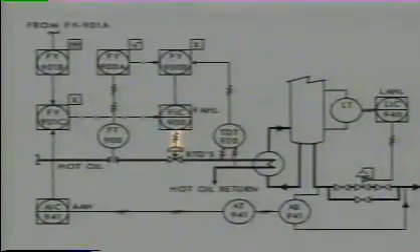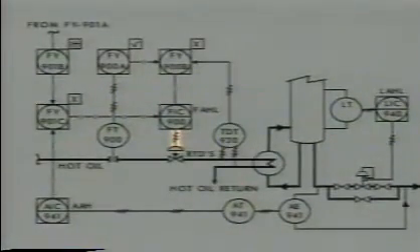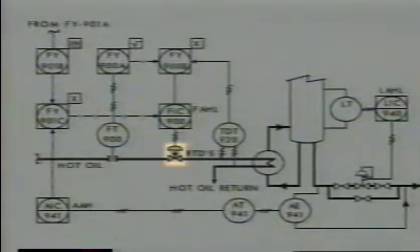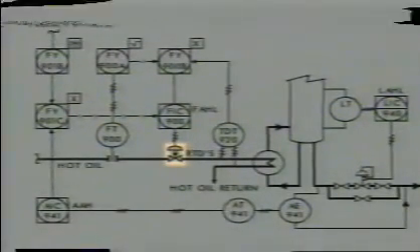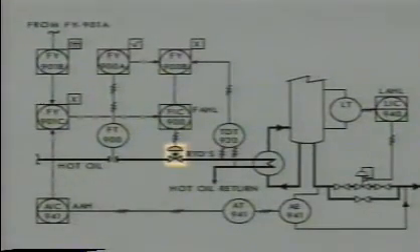The controller sends an electrical signal based on its two inputs to a final control element, in this case, a control valve. The final control element is an electrically actuated two-way control valve, configured to fail closed in case of signal or power failure.